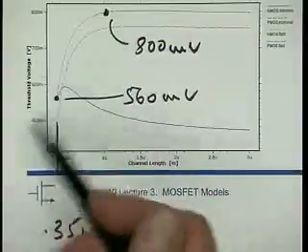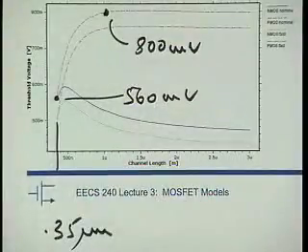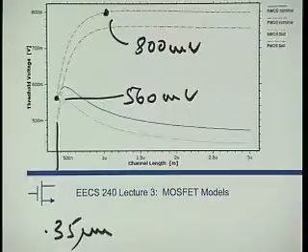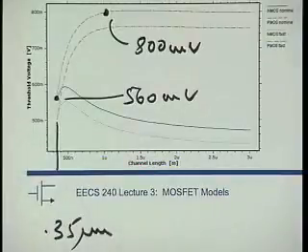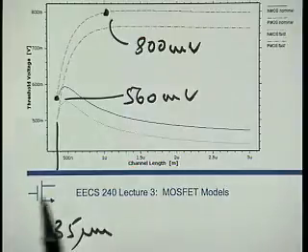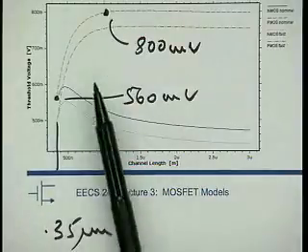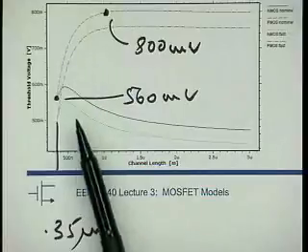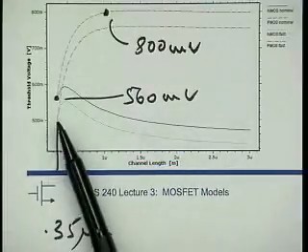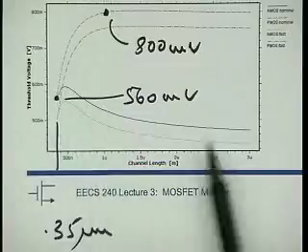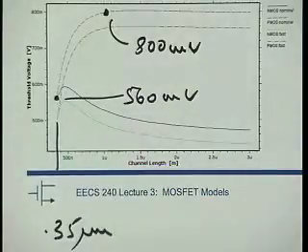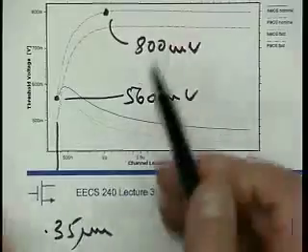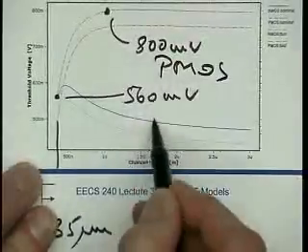It turns out it's not that difficult to calculate, but that depends on textbook examples, and they, of course, assume that you have uniform doping in the entire channel. Well, if you don't, then things can be quite different. And so manufacturers exploit that; they use complicated or clever doping profiles that, to first order, correct the variations of threshold voltage. I guess this was the PMOS actually I showed here, and these two, they are NMOS.